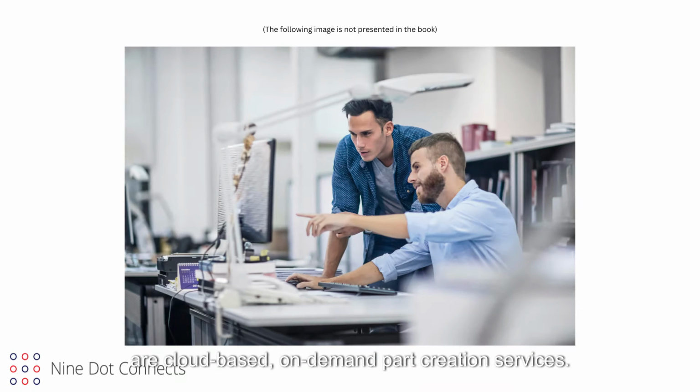Some are cloud-based, on-demand part creation services. Some are very extensive libraries, provided by large part distributors like DigiKey, or commission-free databases like Octopart. With all that, it is still the designer's responsibility to verify any component data from a third-party source. There is a fair chance that the part needed is not available through these channels, so be prepared to create your own.